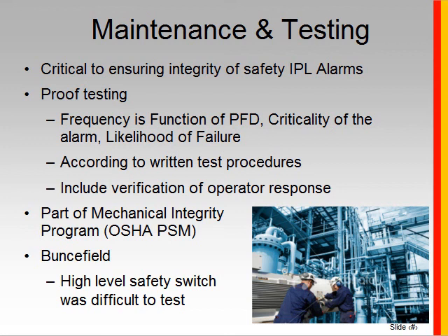Now, again, referring to the Buncefield example, that second layer of protection, the high-level safety switch, one of the issues with that was that it really was untestable or unauditable. It was located on the top, the roof of the tank on the inside, in a location that really couldn't be accessed to test.